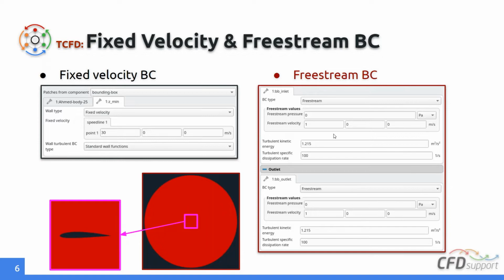So the free stream boundary condition remains the same, and you can, for example, in the TOpt, parameterize or optimize, looking for the maximum drag coefficient or minimum drag coefficient or maximum lift coefficient via the angle of attack or via the inlet angle. So now you can use it in a pretty straightforward way.